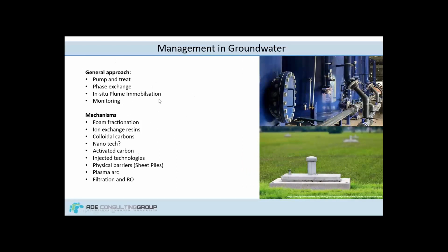And groundwater is quite a similar thing to the wastewater that I discussed. Key ones that I wanted to highlight here are injection technologies, such as colloidal carbons. There's a few nanotech options here as well. And then also physical barriers, stopping the groundwater from flowing to places we don't want it to go. So these form, again, under pump and treat.